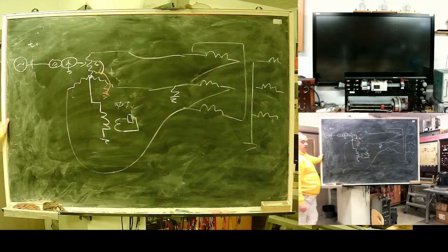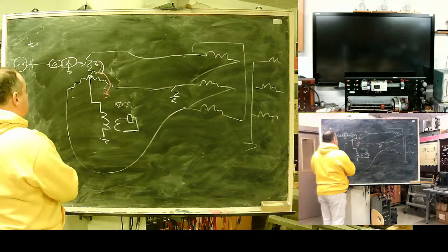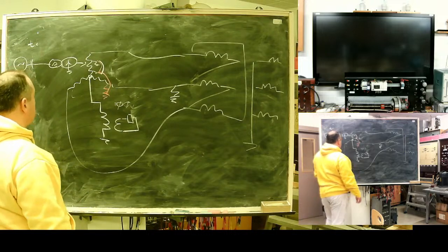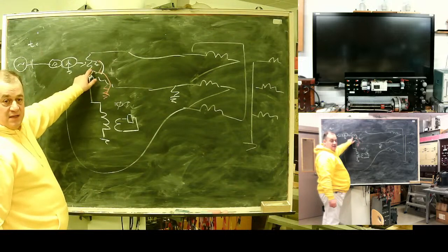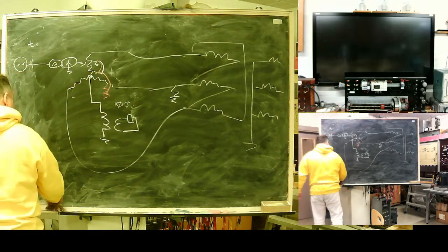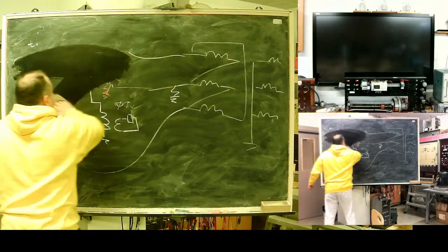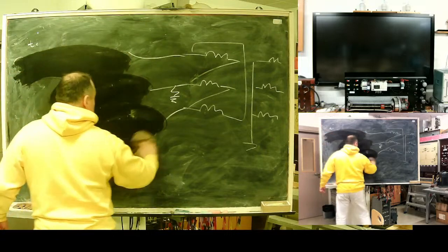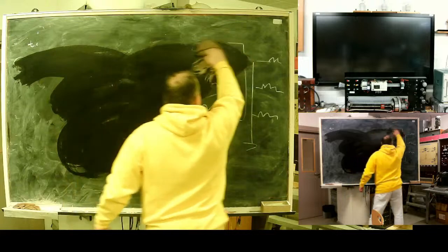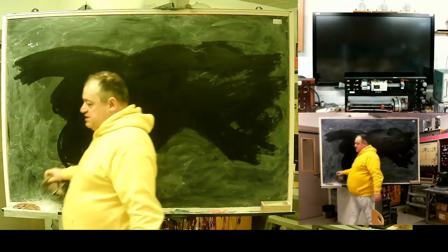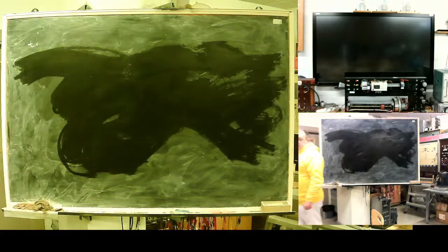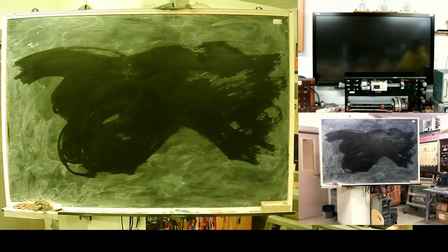So we need very specific earth fault protection, able to detect earth fault near the neutral. Good practice is to equip our generators with third harmonic differential protection.